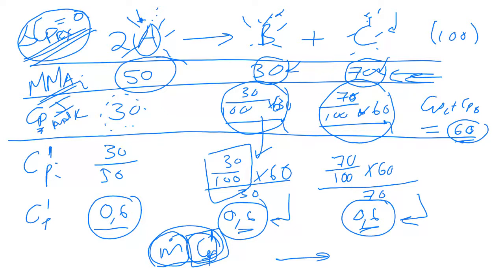It doesn't need to add up, because the fact that the carbon is now bonded to an oxygen, or has a double bond, may mean that it changes its energy carrying capacity slightly, but not by that much. So it is often a very good assumption to make that this del CP is equal to 0, therefore the mass-based CP value of each of the flowing streams stays exactly the same.